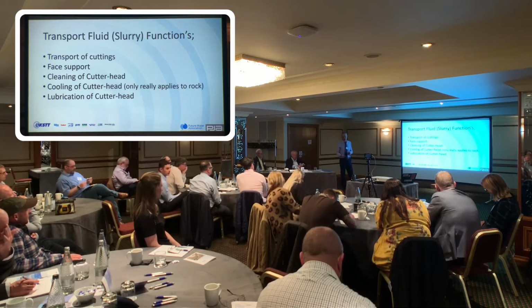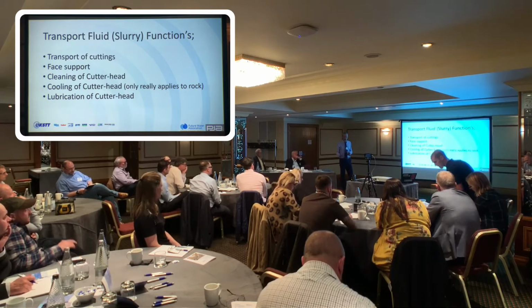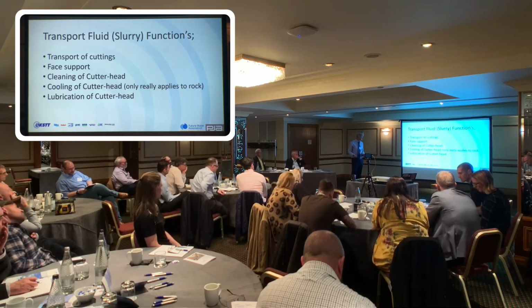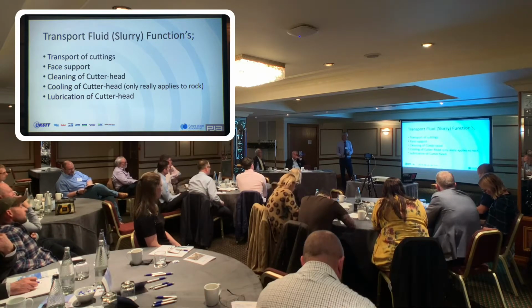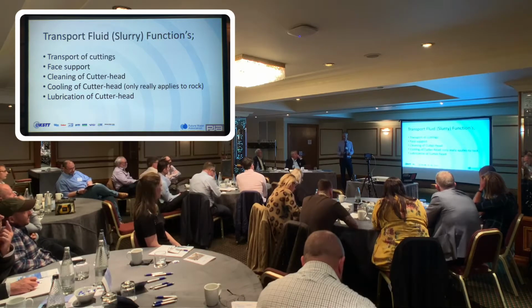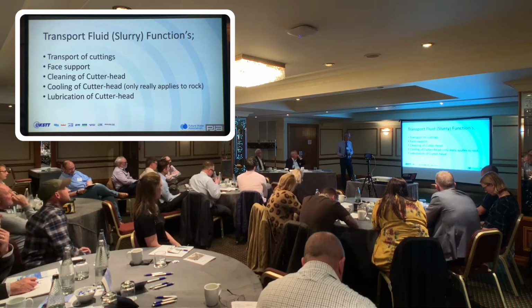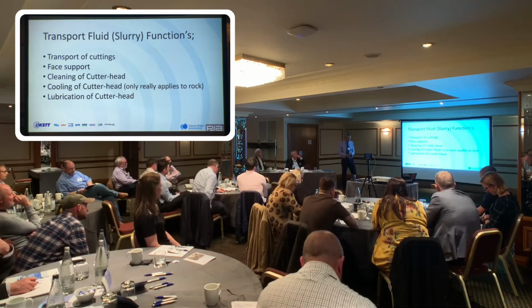It also cleans the cutter head, so in clay soils which have a tendency to stick, the slurry is there to keep the cutter head clean and working at its optimum. In some situations you might want to be cooling the cutter head. That really only applies in rock, where you've got high strength rock turning cutting discs, and it also provides some lubrication to the cutter head.